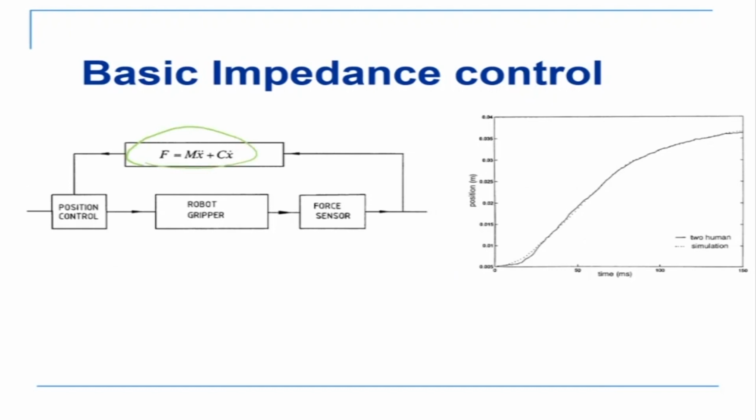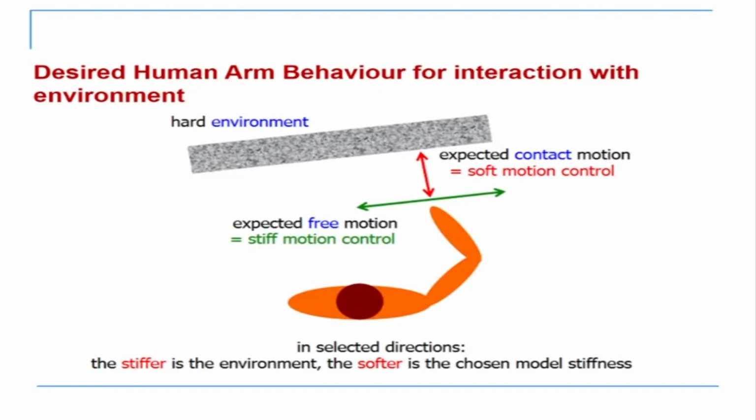Okay, now these are called basic impedance control structures, in which the robot can actually behave like a human. Fundamentally, this is how robots interact with rigid environments, and the only way it can interact is by making an assumption that F is equal to K into del X. Let us say there is a small deflection del X, and there is some K there. So by modifying this K, you can make the robot behave in a particular way.